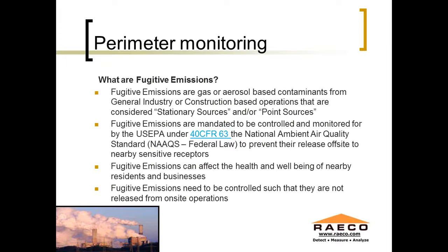The reason we're doing fugitive emissions outside is typically we're compliant to the US EPA under their National Ambient Air Quality Standards. For instance, under that standard, for 24 hours the US EPA dictates you have to stay below 150 micrograms per meter cubed.